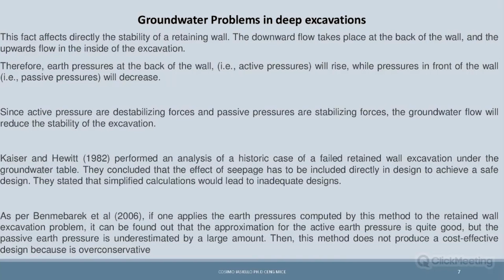The important point is what I told you about the earth pressure at the back of the wall, which will rise while the pressure in front will decrease. This is important. This is case 7, how we studied that: the analysis of historic cases of retaining excavation under the groundwater table. This means that the effect of seepage has to be included directly in the design to achieve a safe design. And they stated that simplified calculation would lead to an adequate design.